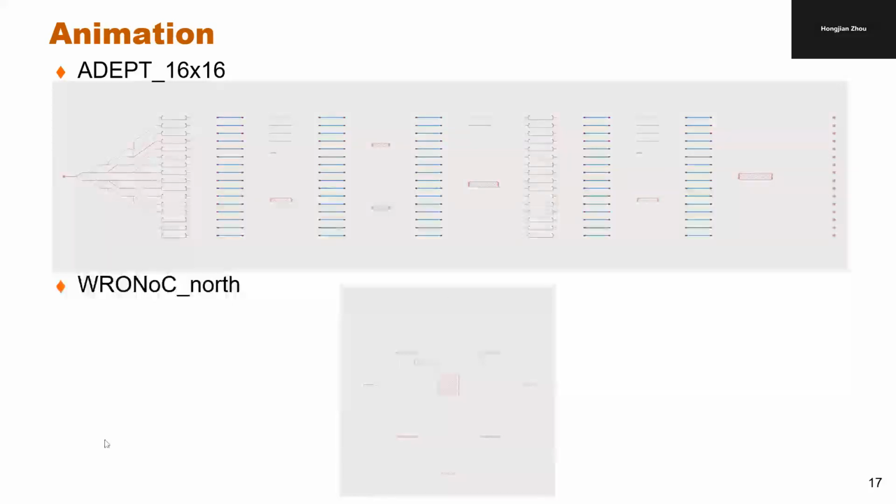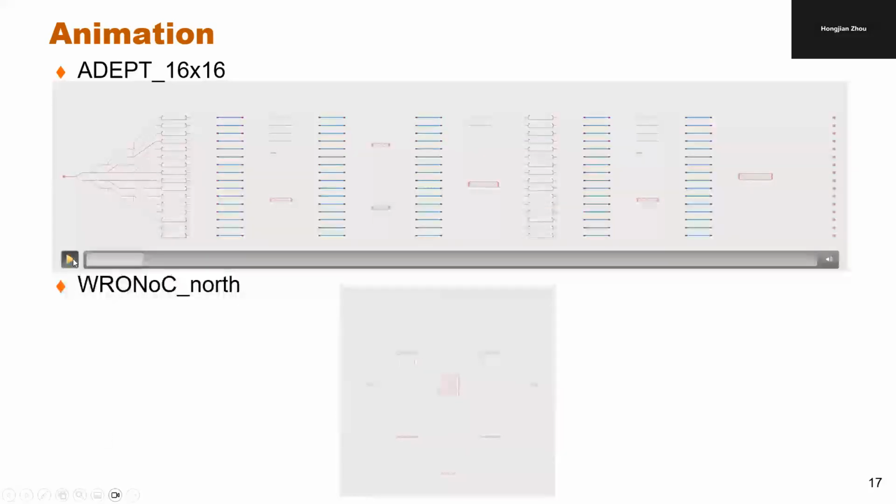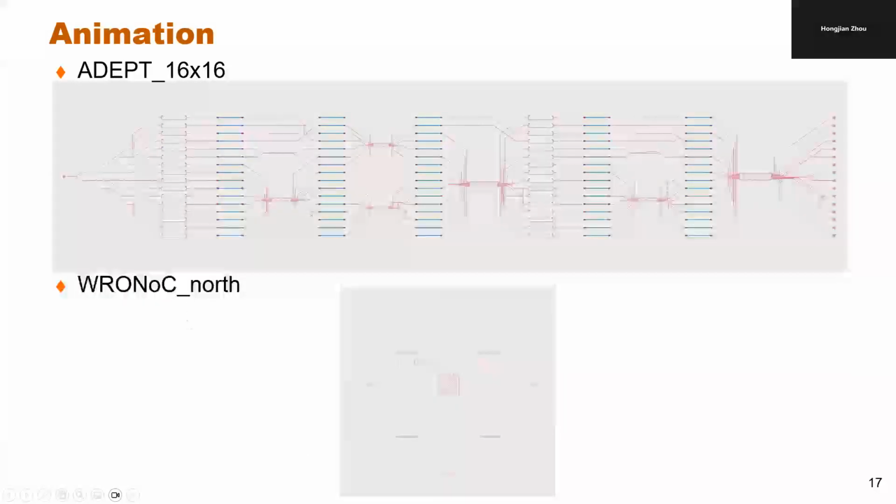Here we show the animation of the intermediate routing result. After all the nets are routed, we will instantiate the routed crossings first, and then the connected waveguides. And this animation shows how we optimize the necessary crossings here.